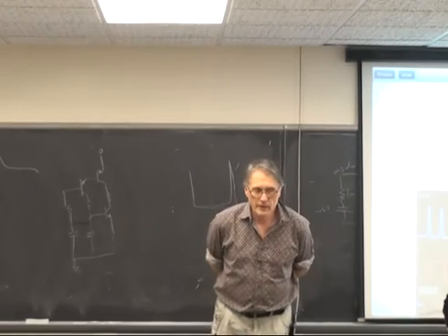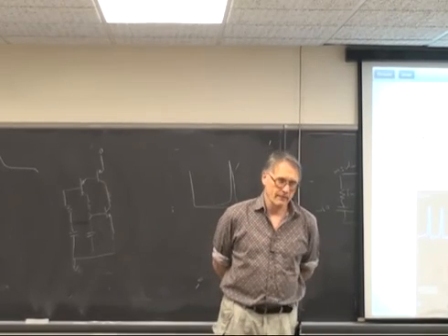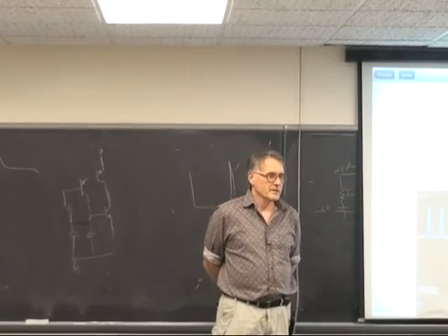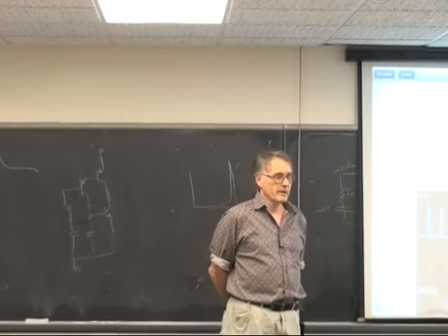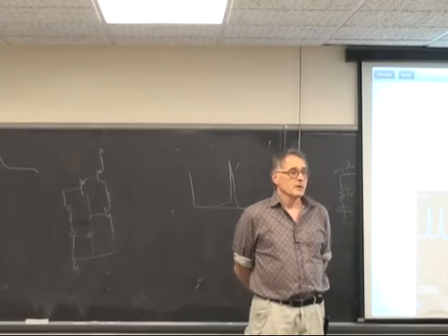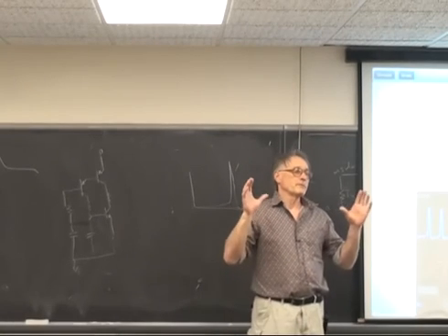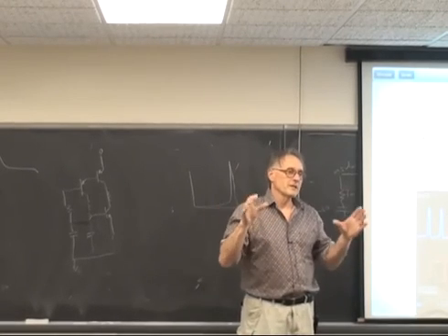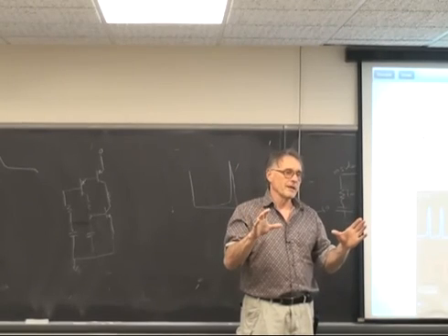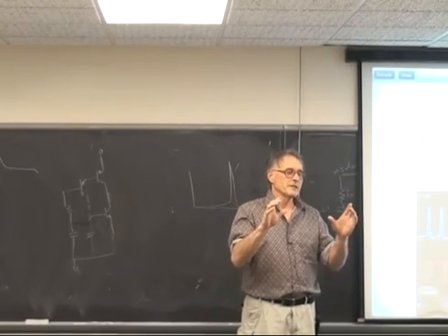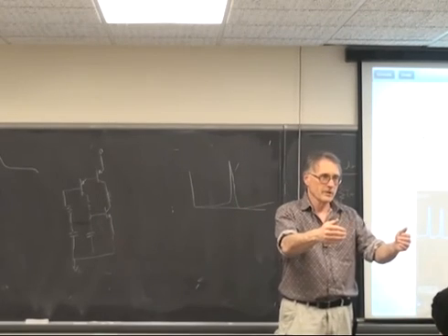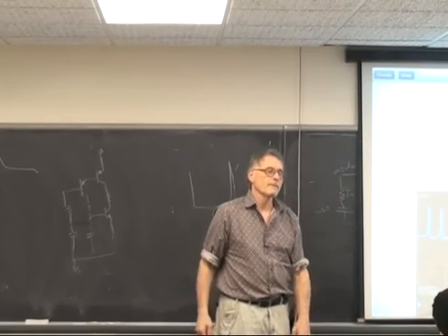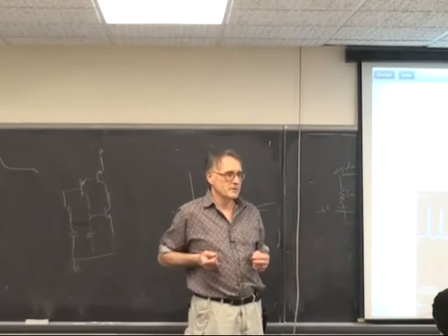Once you have a nonlinear element, that doesn't work anymore. So you have a set of nonlinear equations, and the only way to solve them is by iteration at a time step. So the way SPICE works is it makes a guess about the current dynamic state, and then it iterates it until everything is self-consistent. Then it takes a step forward in the differential equation and does it again. And that can be quite time-consuming.